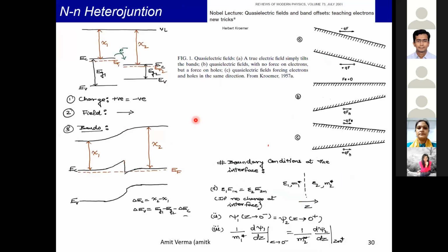So how do we make a band diagram for a heterostructure? Suppose you have two semiconductors, whose details you know: the doping, the electron affinity, the band gap, and the Fermi level. Similarly for the other material. Again, same deal: when you make a heterojunction, the end thing at equilibrium is that the Fermi level has to be flat. In this case, electrons will go from here to here because the Fermi level here is higher. So this side will get depleted, this side will get accumulated.